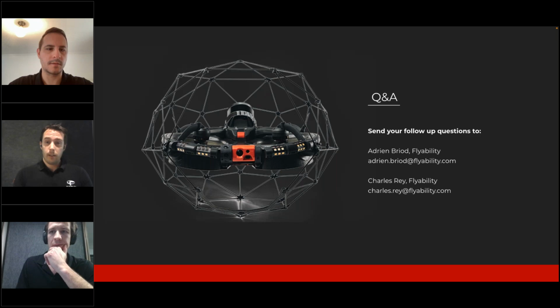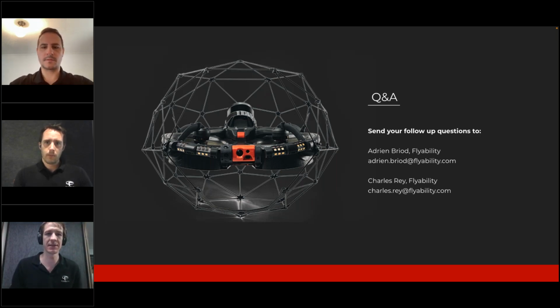Adrien, any idea? Sure. I think for detecting cracks is definitely where you'll want to use the RGB camera, and it's definitely higher resolution than the LiDAR when you do close-up inspection. Cracks are probably more visible visually, and the optimal distance from the wall to capture the most details is about 20 centimeters.